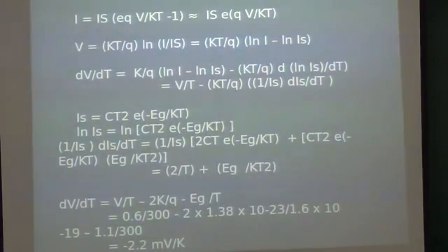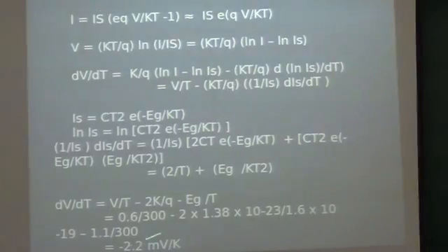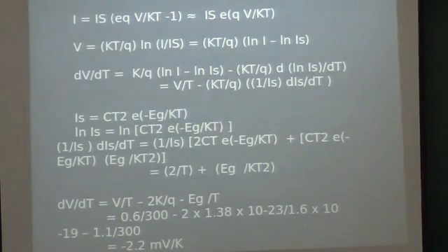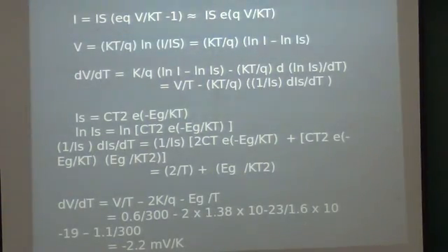So normally for a silicon diode, if we fix a current, the change in voltage as a function of temperature, that is the decrease in voltage, for every degree centigrade rise in temperature will be just 2.2 millivolts. So this fact can be used to calibrate a silicon diode, with a fixed current passing through it in forward biasing condition, as a temperature sensor.